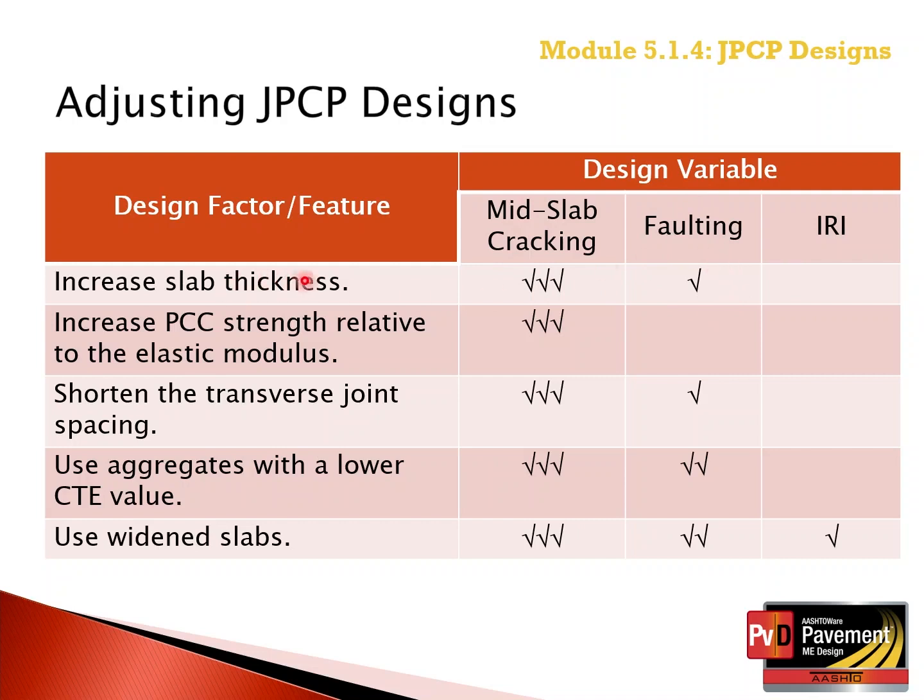So obviously slab thickness does have an impact on IRI, but the majority of its importance is defined through the impact on mid-slab cracking and faulting. So just for IRI, it has a very minimal to nil impact.